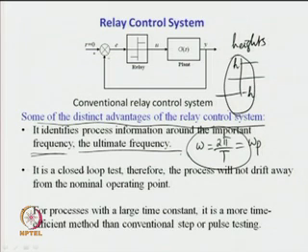Now, this setting h can be of any value. We can go on changing h to any value till we get some appreciable sustained oscillatory output in the output of the closed loop system, which can be measured easily. So, there is no condition for setting the h value.